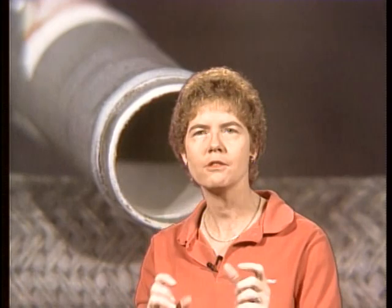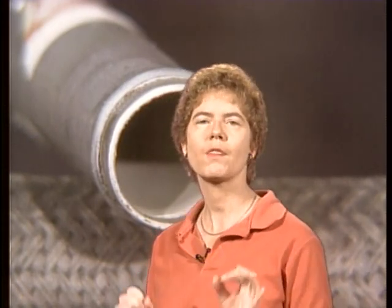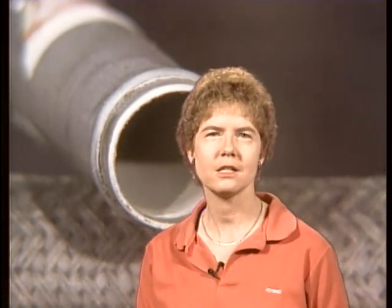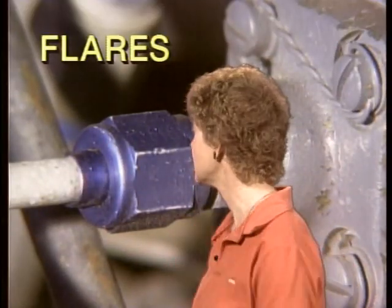So the first number they gave you, the 3/4 inch, was the outside diameter, and the second number, the 0.072, was the thickness of the wall, but you need twice that thickness subtracted from the outside diameter in order to get the inside diameter. Now let's talk about flares and flare fittings.